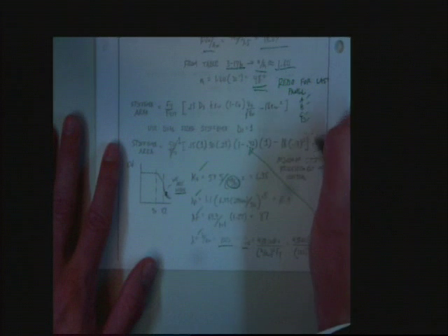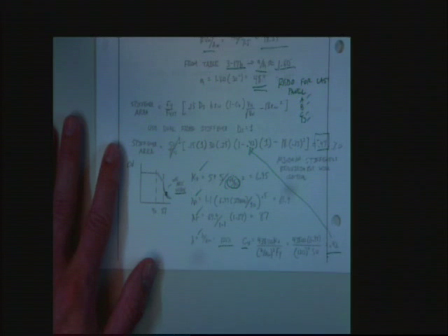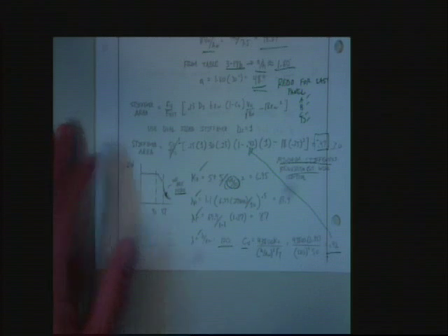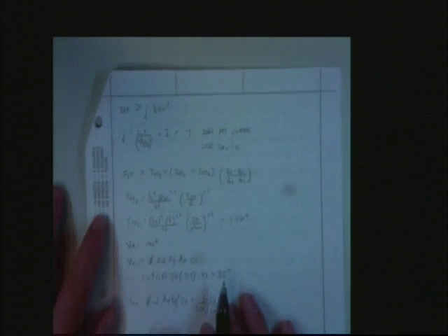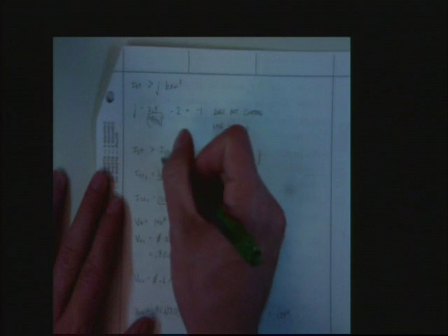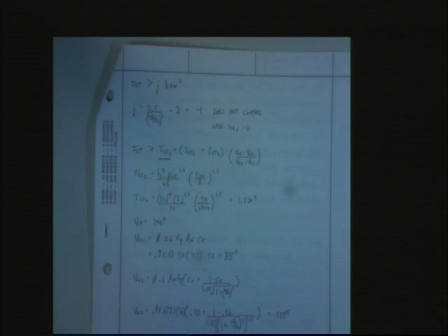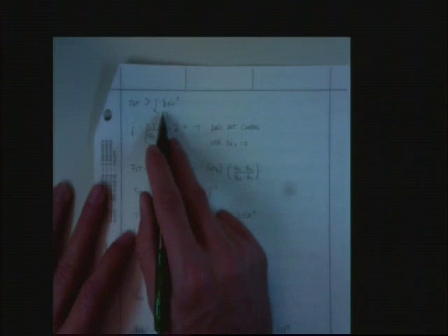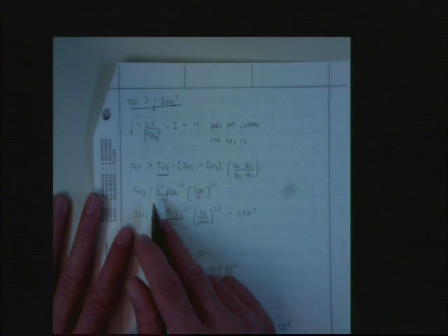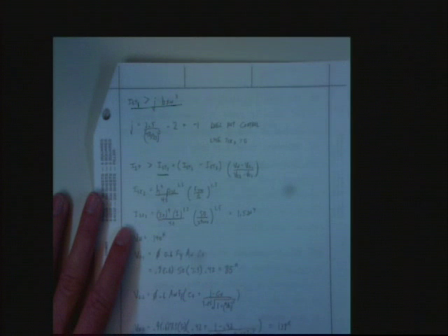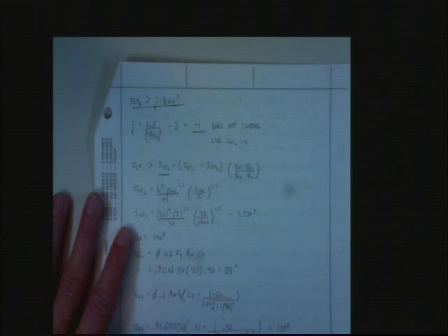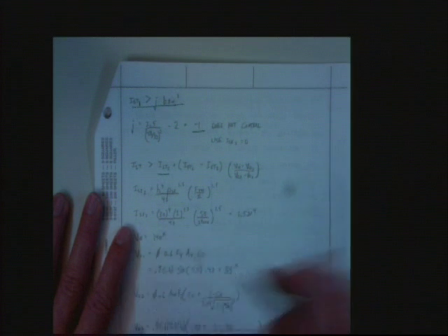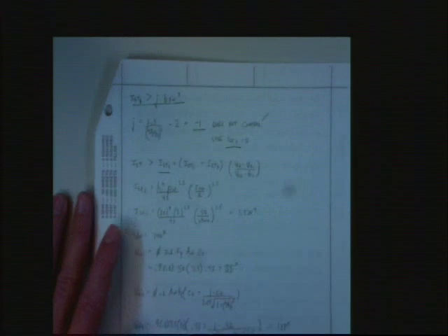But we found out we need a negative stiffener area. That means the minimum stiffness requirements will end up controlling. That's what that means. Flip it over. So now we start solving for our other stiffness. And this stiffness was the same thing as IST1. And if we recall, the true equation for IST1, oh, it's right here. Put it on there. That's IST1. And it's actually a standalone stiffness. We found out when we go to calculate J that we got a negative value. That means it does not control, and we force IST1 to be 0.